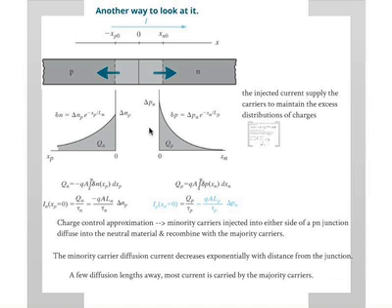They're recombining with some lifetime tau p. So every tau p seconds, which is the average lifetime of the holes, you have to replenish this charge, which is the injected current. So you can think about it that way as well. It's a time-dependent capacitor which is getting replenished. The charges are getting replenished, so you can calculate the current that way as well, which is what's shown here.